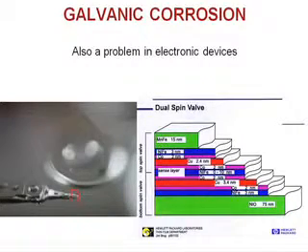And here's the structure of a very sensitive sensor. It's called a spin valve. And we see that there are layers of different materials that are put down on top of each other. We have cobalt and copper, for instance. Cobalt is down towards the bottom of that galvanic series. Copper is well above it. And what happens actually is that a cross-section of all these layers gets exposed on the surface of this sensor. It's more or less exposed to the environment. So we can see that this is a galvanic corrosion nightmare.